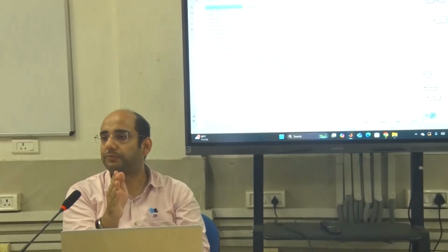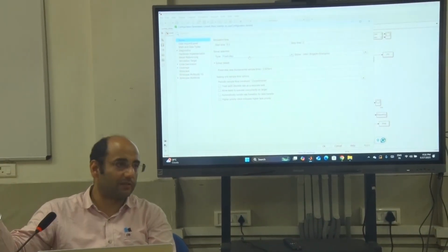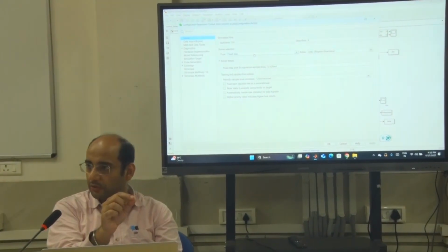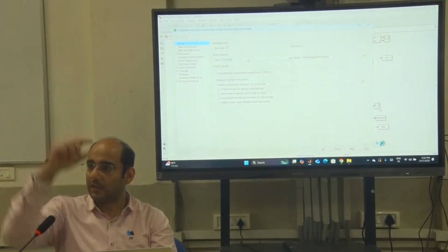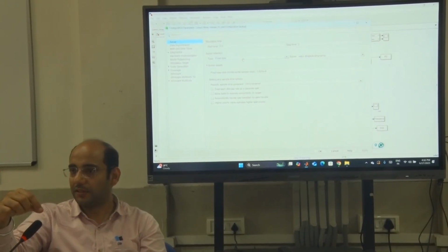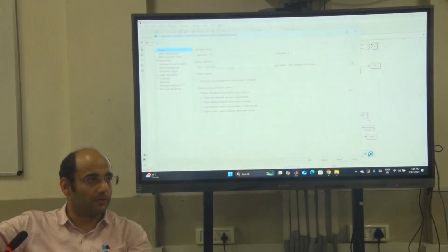Let's go one more step. Instead of 10 milliseconds, what if I simulated at 5? 0, 5, 10, 15, 20. You have 20 milliseconds in one cycle. First sample at 0. Next at 5 milliseconds. What value will you sense? The peak. Then 0. Then the negative peak. Then 0.